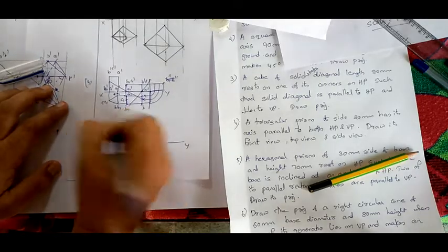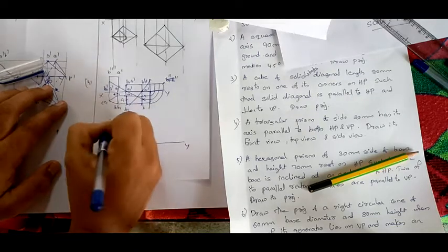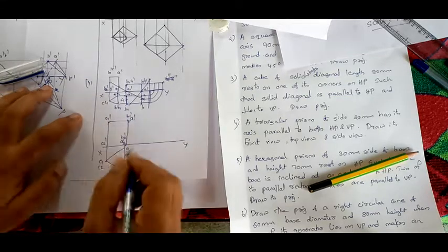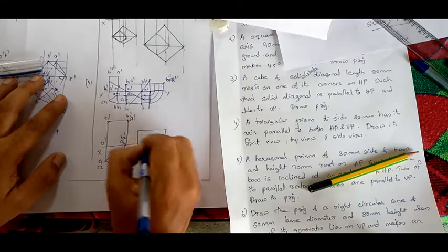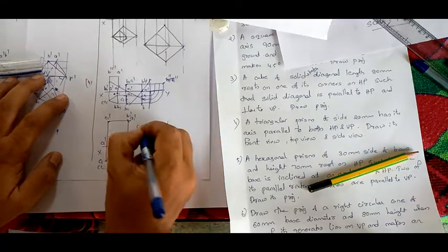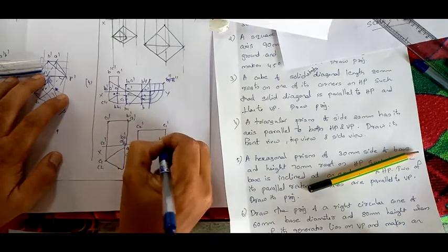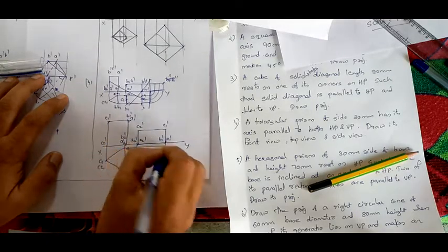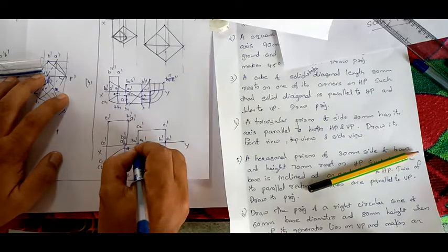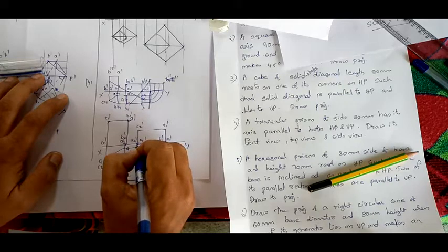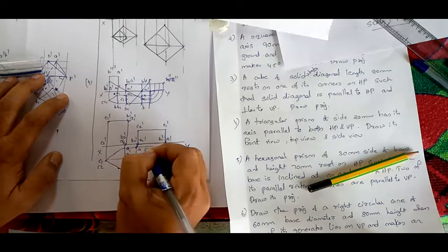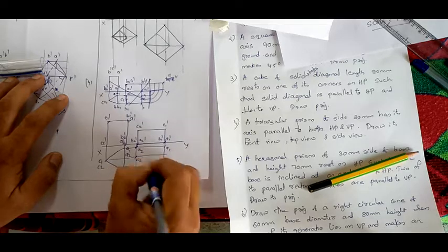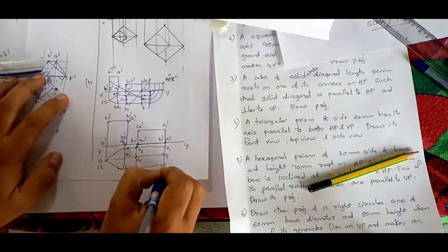In the top view I am giving A1 dash, B1 dash, C1 dash. Here A2 dash, B2 dash and C2 dash. Now we are rotating and making it parallel. Then this is C1 dash and this is C2 dash, this point is B1 dash, A1 dash, and this point is B2 dash, A2 dash. Now project to obtain the corresponding view. This point is your A2, this is your A1, this is your C2, this will be your C1, this will be your B2, this will be your B1.